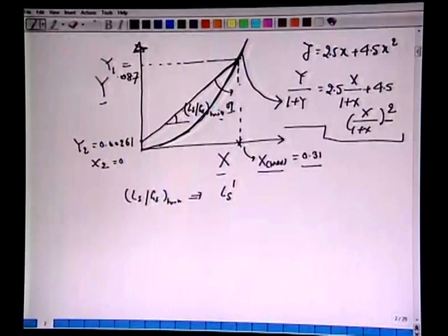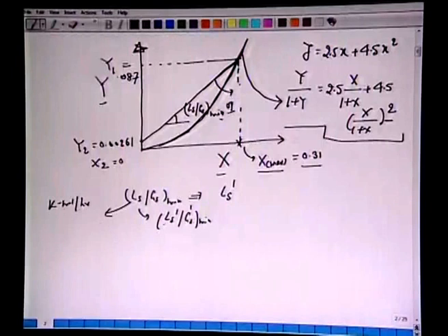So note this here. So far we have been used to plotting LS by GS, but LS by GS is the same as LS prime over GS prime. So this is kilomole per hour or per second. This would be kilomole per hour per meter square, so, cross sectional area of this column.